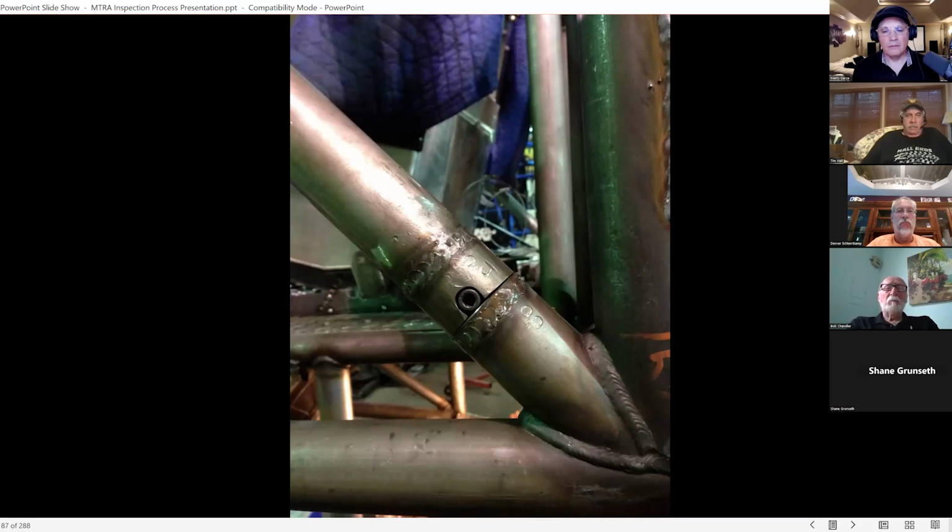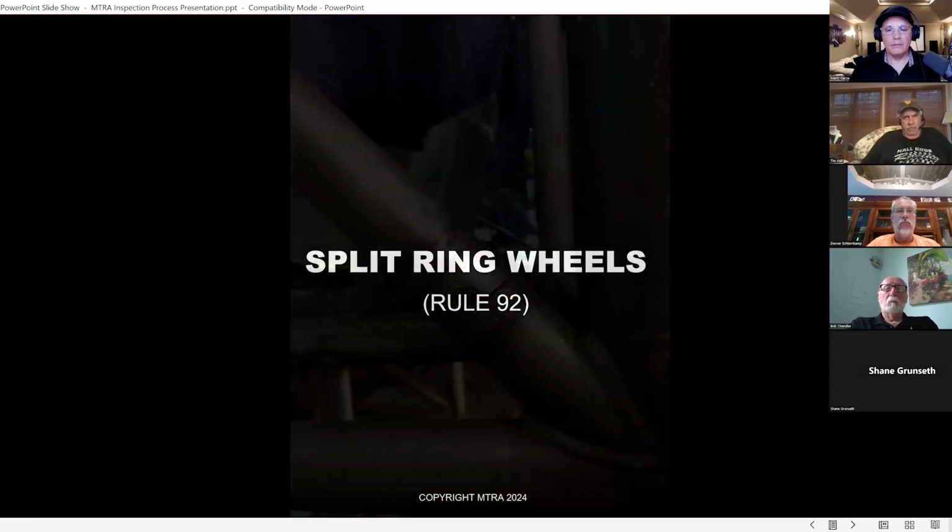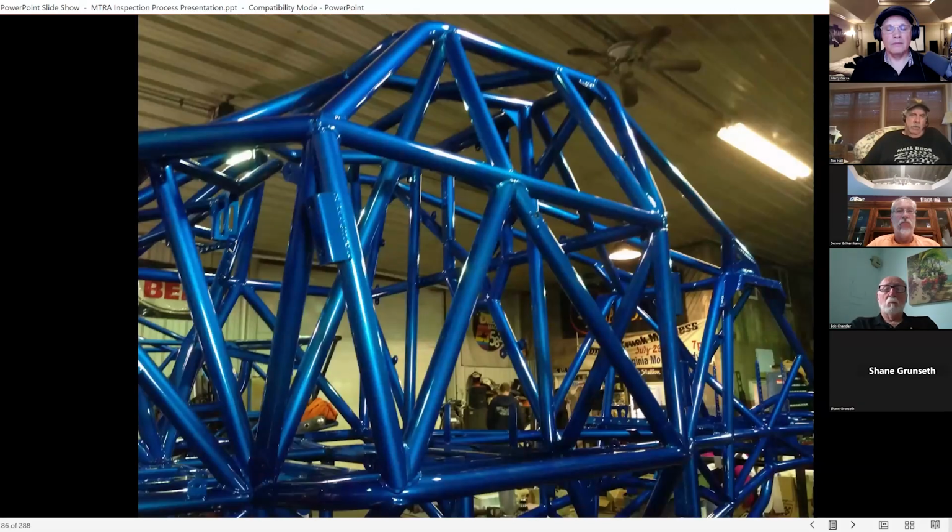You can look at it and see. One of the things when you're inspecting a truck and looking at these cages is to look at the welds. You've got to be looking for workmanship. It's very important. Welds that aren't done correctly are destined to fail. Not only whether the material's right or not, but if the weld's not correct, it doesn't even matter. So you've got to have the right welds. Be looking for that.